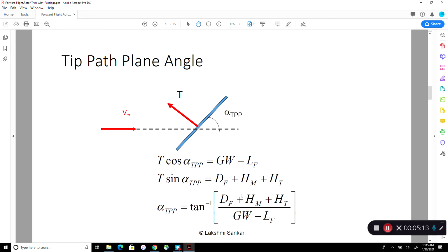Now, unfortunately, it contains lots of stuff in here, which depends on the vehicle orientation, the fuselage angle of attack, for example. Just like an airfoil, if you pitch it up or down, the drag will change. If you rotate the fuselage up or down, it's going to produce drag force and also lift force, depending on its orientation relative to the oncoming free stream.